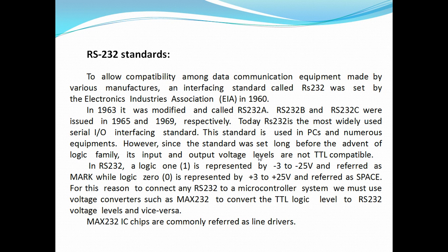So to have communication between RS-232 and a microcontroller, we have to use the MAX232 IC for converting TTL logic levels to RS-232 voltage levels, and vice versa.